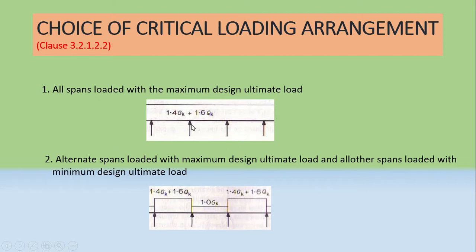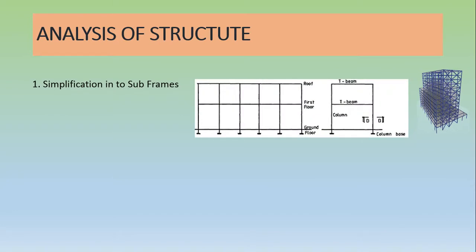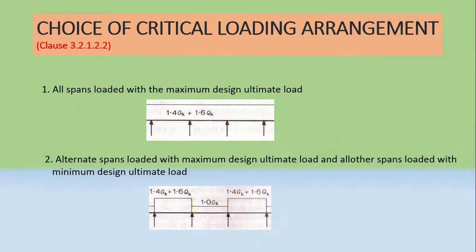We have to consider all these load combinations, because the whole beam is not fully loaded at a time. Sometimes it may be partially loaded like this. On these two occasions there are different bending moments and different values of internal forces, and those have to be calculated.